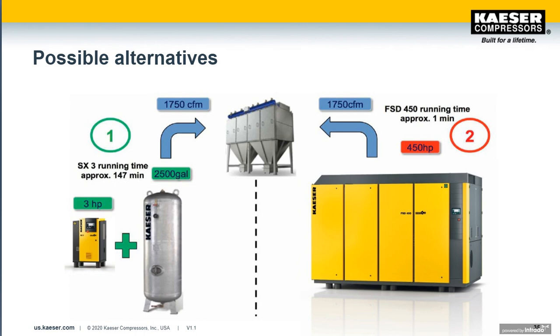The key to sizing any event like this is to know that required flow, required pressure, the event duration, and the amount of time to refill that storage receiver. In this particular case, either the 3 horsepower with the storage or that 450 horsepower compressor could meet that 1,750 CFM demand event. However, keep in mind the utilization of either compressor.